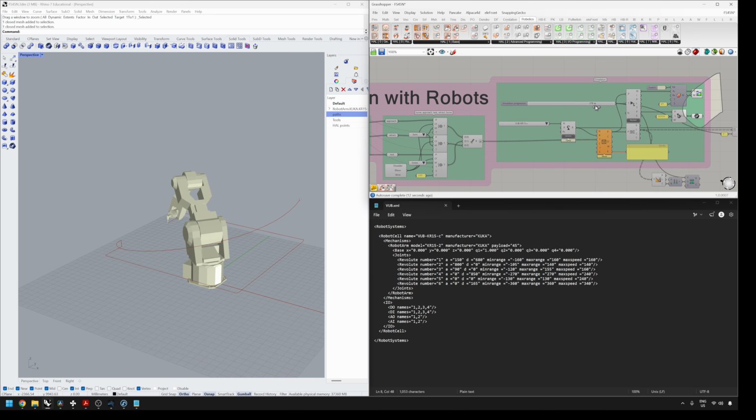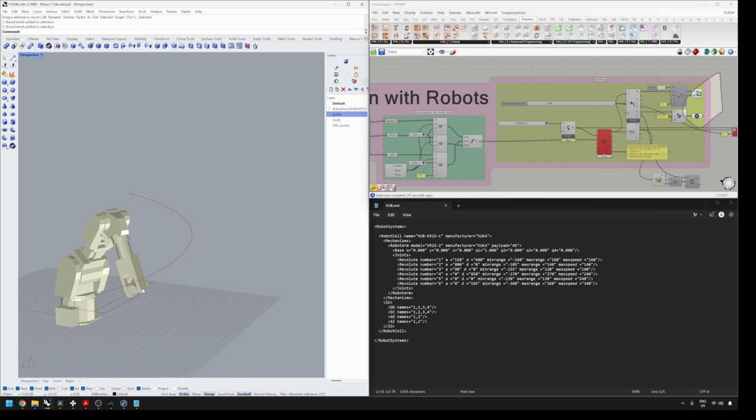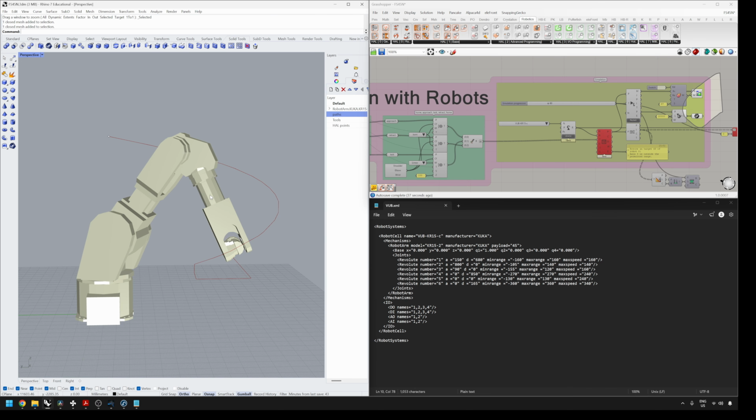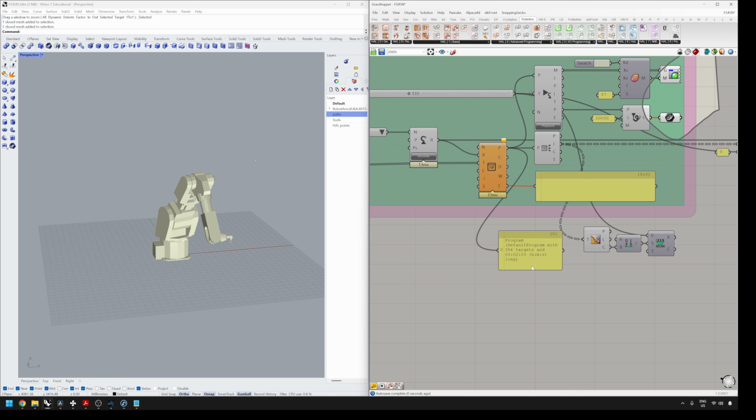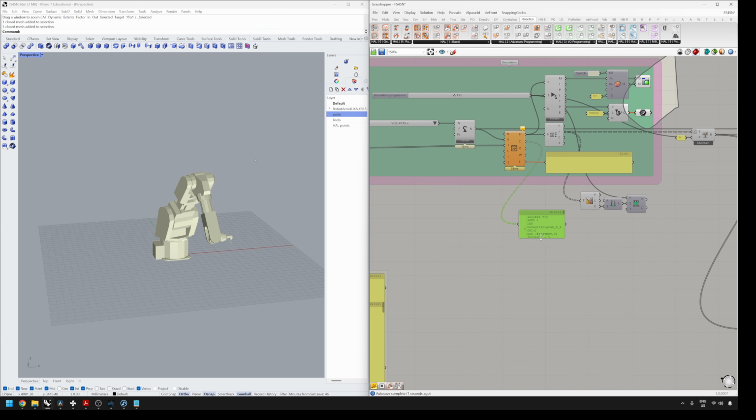It was also necessary to deviate from the manual's joint 3 minimum and maximum values because the robot's plugin reported axis 3 errors in positions that should have been valid. There's nothing wrong with this position. Axis 3 is not outside of the permitted range. Although changing the limit removed those errors, it also raised doubts about the reliability of the plugin's internal kinematics and program output when applied to a Kawasaki robot.